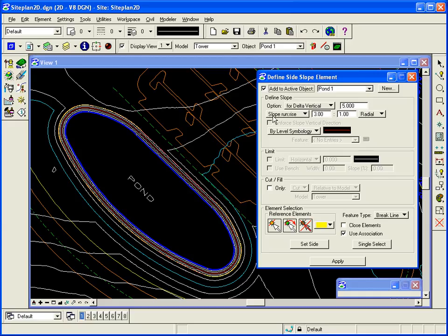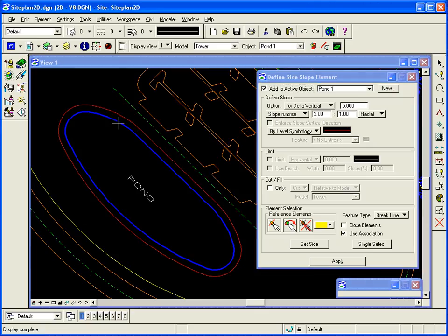Now let's continue with the pond and the pond berm. Previously we established the bottom by just simply taking the blue graphic, setting it 4 feet below ground. Then we came up 5 feet at a 3-to-1 slope. That established the inside edge of the top.